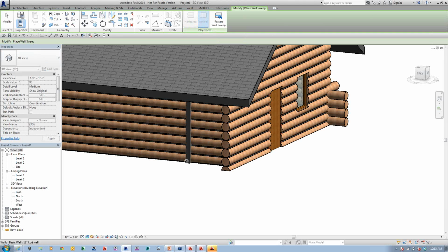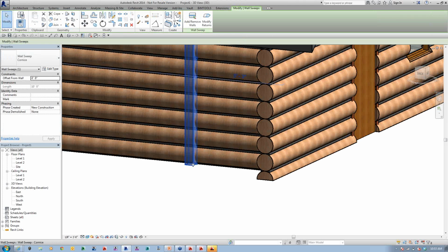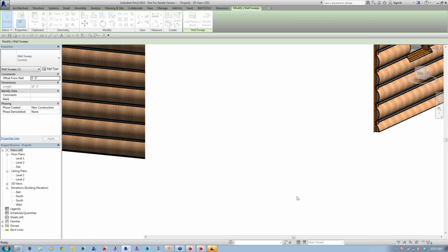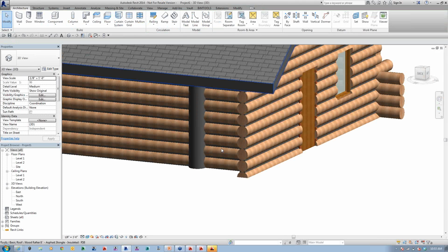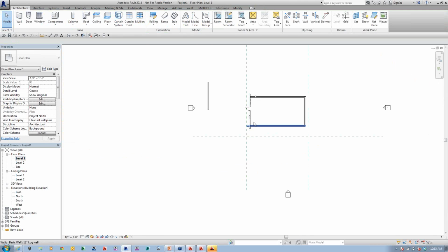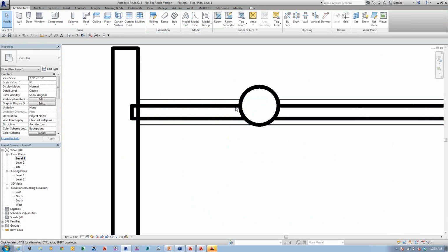And here you can see I've got a vertical sweep. Now, this is the generic sweep inside, but I can select that wall. It has the default profile, but remember, we've just made profiles. I'll come inside and say, oh, I need an 18-inch log, and I'll put that in there, and now I've got that 18-inch round log there. Now, where is it being placed in the wall? Well, we need to go back and see, and it places on the exterior edge of the wall, not the sweep.